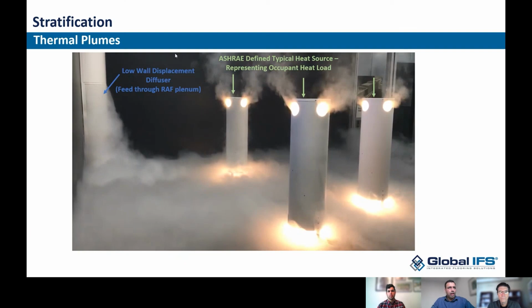And what I also like to point out with this video is, this is science. This is how it works both biologically and physically as well. Biologically, we're designed to add heat to the space, and hot air always rises. It never fails to repeat itself. As long as you have heat sources within the space itself, the cold air that you're bringing in through your floor diffuser will find the heat source, because again, it's the heat source that's driving the air movement within the space itself.